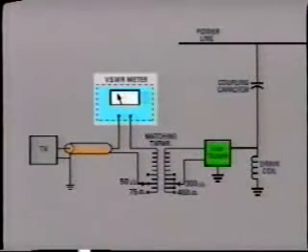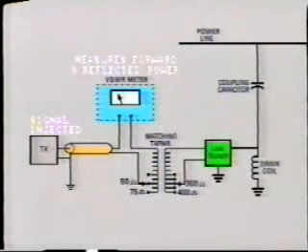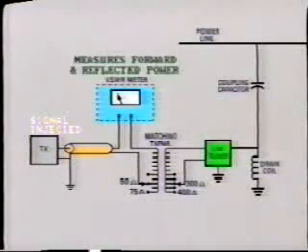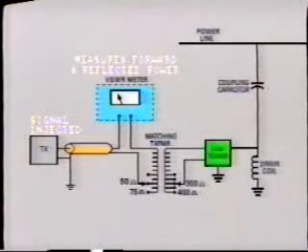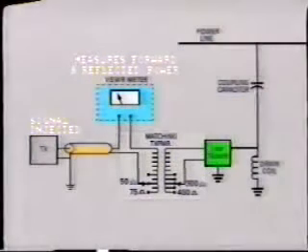The meter is usually connected into the circuit between the incoming coaxial cable from the carrier and the coaxial terminal connection on the LMU. A carrier test signal is injected at the appropriate frequency, and the meter measures both forward power and reflected power. The taps are adjusted so as to achieve the minimum value of reflected power.